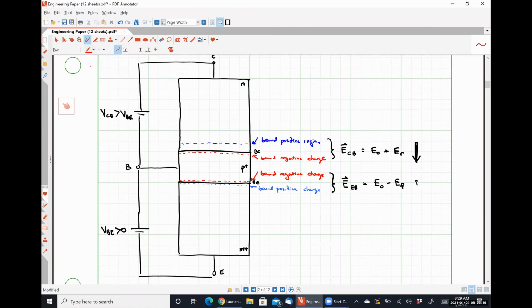All right, so electrons. Let's talk about what's happening in our forward bias junction first. Okay. So under forward bias conditions, our barrier potential is decreased, which increases the probability of diffusion of minority charge carriers. So effectively, we should expect to see electrons can diffuse from the emitter into the base region. And we should also see that holes can diffuse from the base into the emitter. So electron diffusion is going to look something like this.